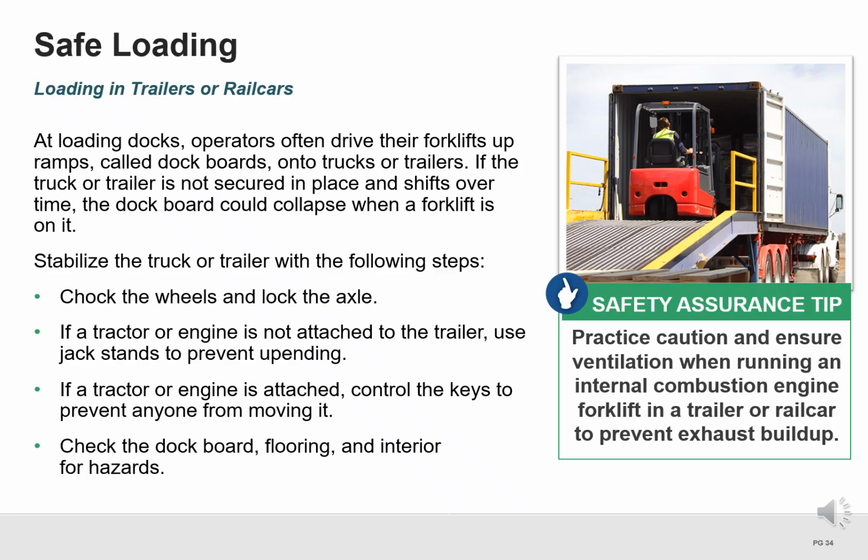Chock the wheels and lock the axle to prevent movement. If the trailer is not attached to a tractor, use jack stands to prevent it from tipping. If a tractor is attached, control the keys to ensure no one moves the trailer during loading. Always check the dock board, trailer floor, and interior for any hazards before entering.